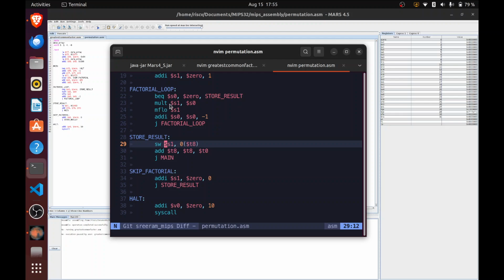What happens is that if both operands are 32 bits, the result is going to be 64 bits, so there will be a higher buffer and a lower buffer. Since for multiplication we are not going to use huge numbers, you can just load it from the lower buffer. So the move from lower buffer command is what I have used here for this register.